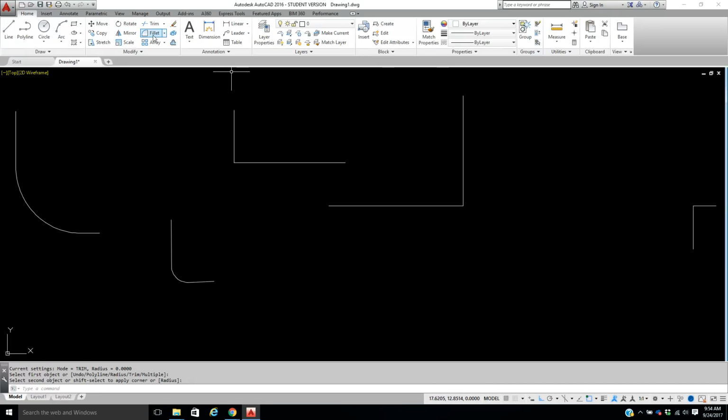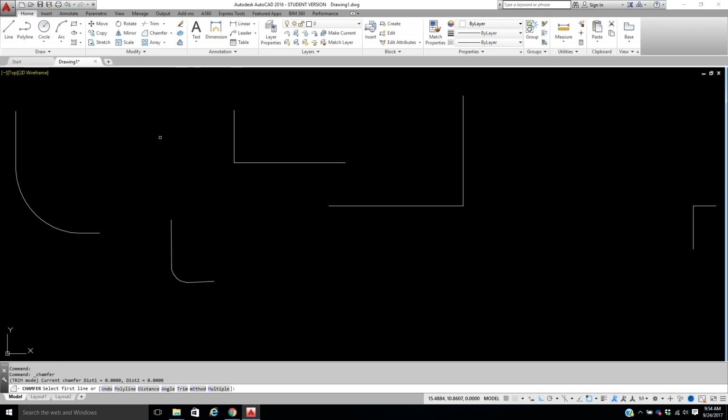Now I'm going to go into the chamfer, and I'm not going to go into the chamfer too much because plain and simple with chamfer, it is the same things as we did before. We can come in down here. We can do a distance. We can do an angle.